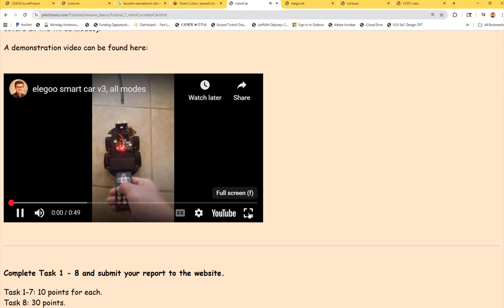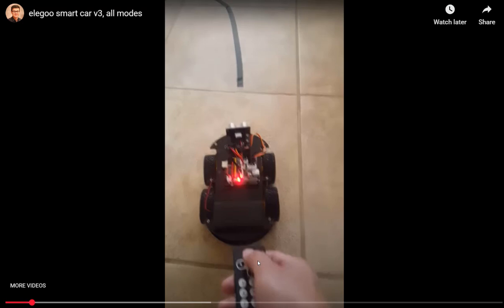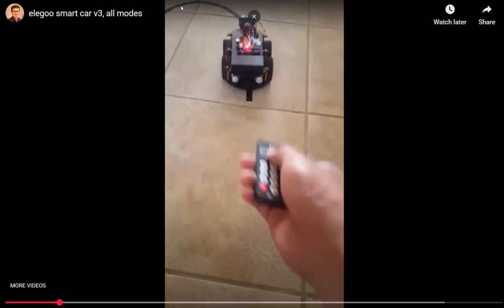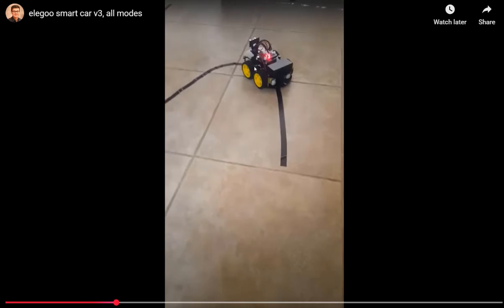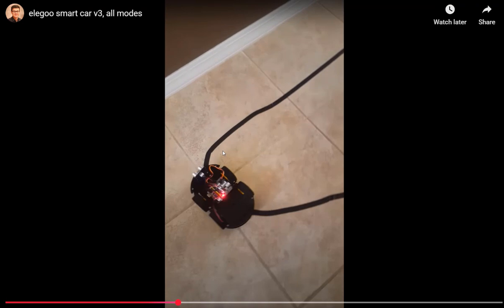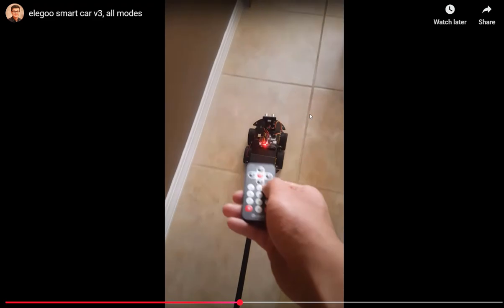So what the robot can do is really simple. You can use a remote controller to control it. There's a receiver on the robot, so you can receive the IR signal and it responds to it. You can start it, and whenever it's on top of the black tape line, it starts tracking that path. Because it has IR sensors at the bottom, it detects the relatively lighter surface of the floor. Whenever it moves onto the darker tape, it senses it and then corrects itself.